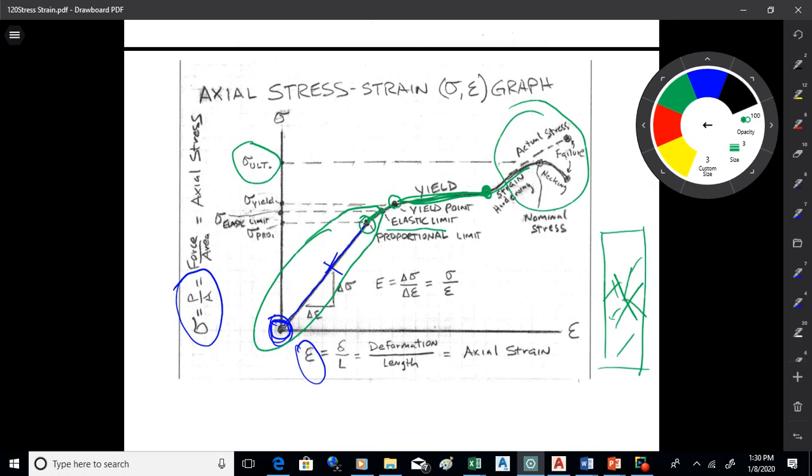If you look at like sword manufacture back in the day, they wanted the core of the sword to be ductile and flexible. They wanted the edge of the sword to be strong and brittle to hold an edge. And so, they did things with annealing, and they did different material properties that they learned by trial and error. So right in here, normally there's a trade-off between ductility and softness, so how much it'll stretch and how soft it is, and hardness and brittleness. So a hard material is often quite brittle too. So you can do different things to play around with the materials.